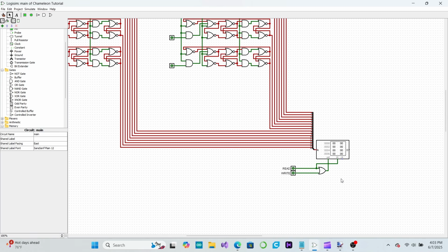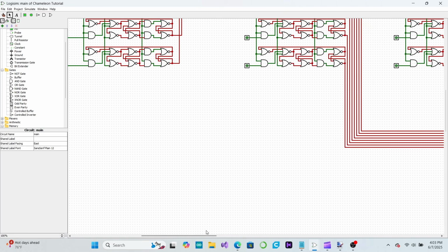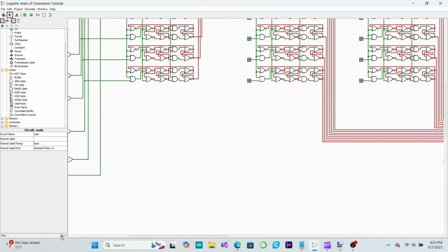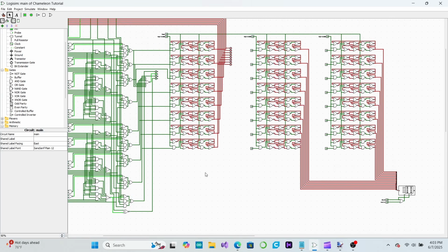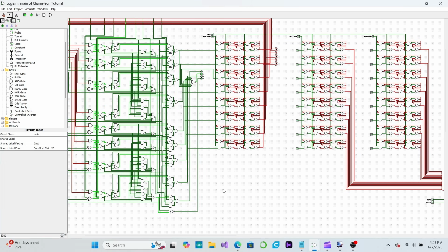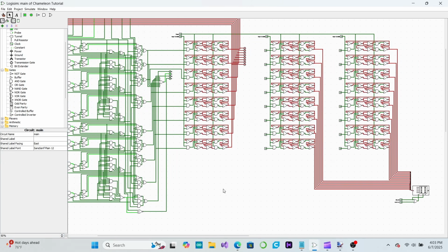Now that we have multiple registers and the ability to access RAM, we will need to add a data bus to our CPU. A bus is simply a generic term in computer architecture for some wires that we use to transport data from one location in our computer to another. For our data bus, we'll simply use 8 wires. Each wire will have a pull-up resistor attached to it. This will make it so that the data bus will always contain all ones unless something else pulls the data wire to ground.